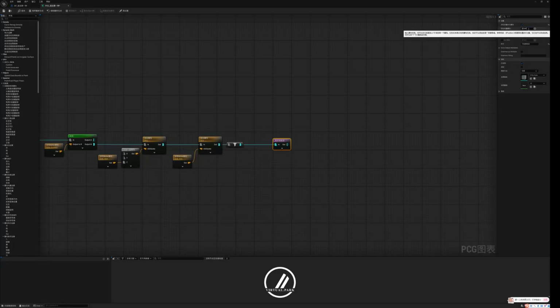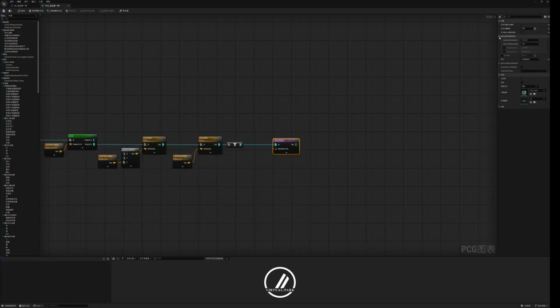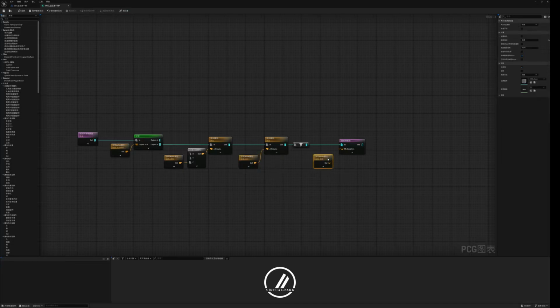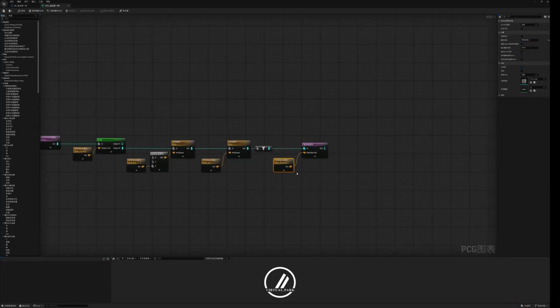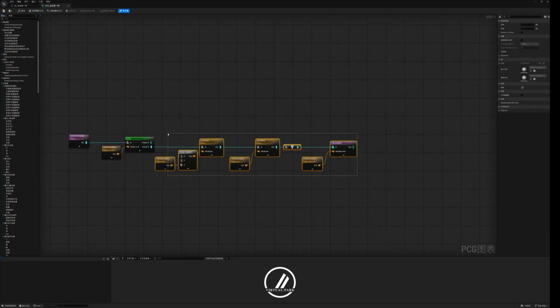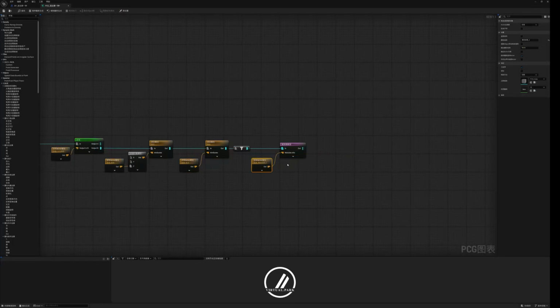In the duplicate cross-section node, you need to check the extrusion vector as an attribute, and then write the previously added extrusion attribute here. In order to write our module information using the blueprint, check the module information that serves as the input. Finally, add the syntax attribute to it. Here, let's write the variable as module information underscore z. These 3 nodes can be used to generate the model of each floor.